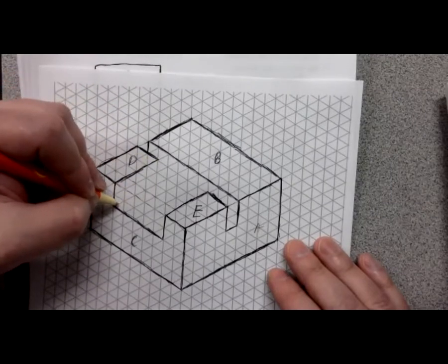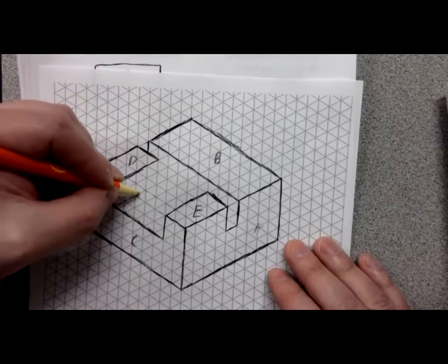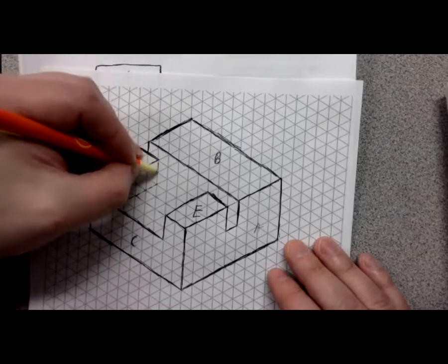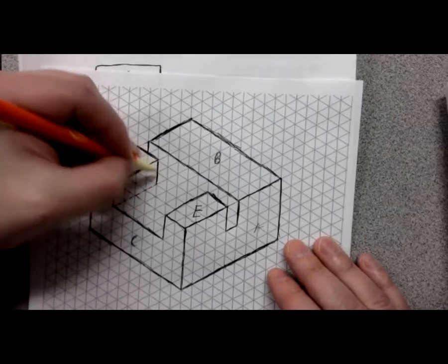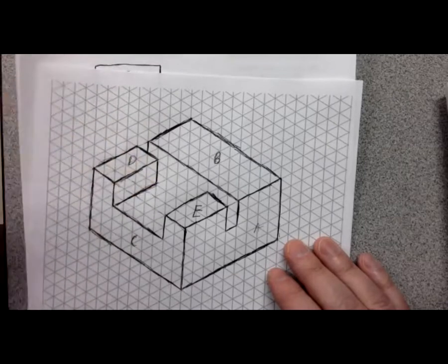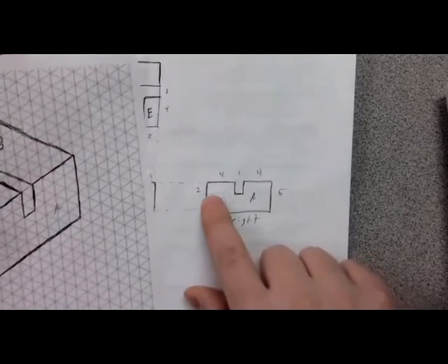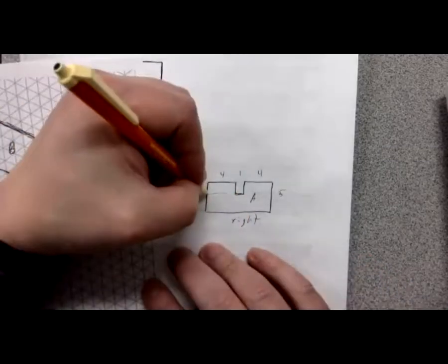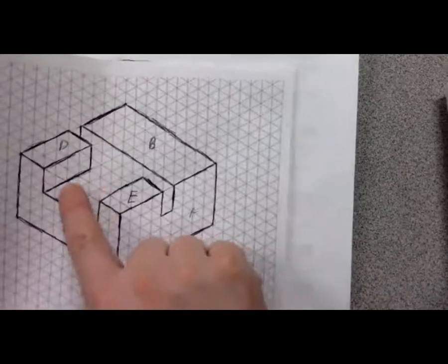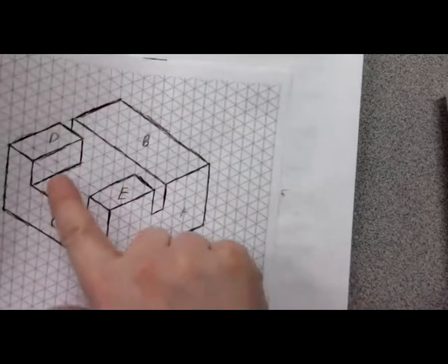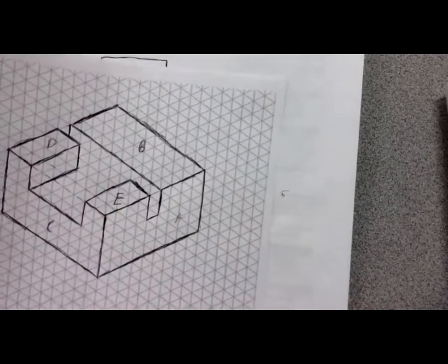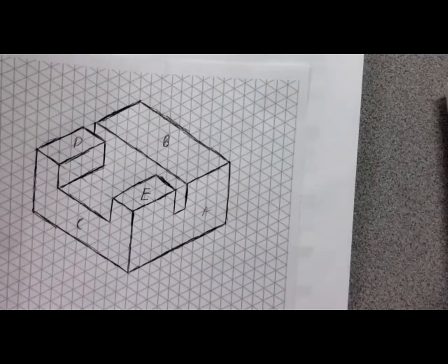So from this corner right here, I'm going to dot in 4. So it's 1, 2, 3, 4. And it's too tall there. Something I can't see would be a hidden line. Right here would be a hidden line. This would be a hidden line right here, would be this one. There's one here behind that we can't see. That would also be hidden, but we don't necessarily have to add that here.